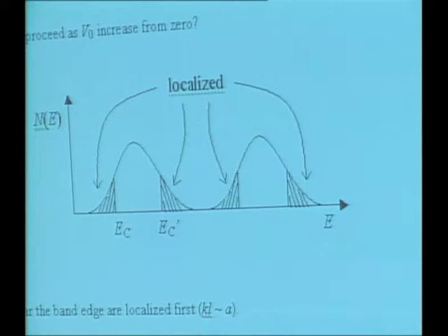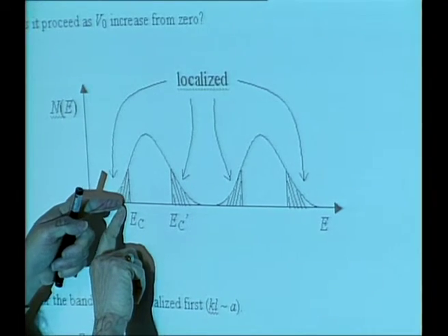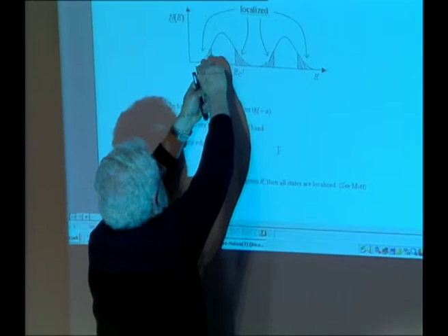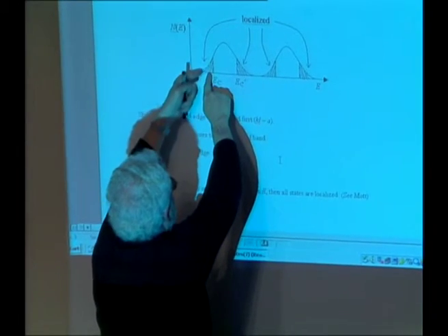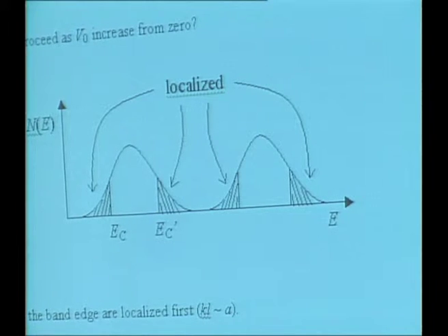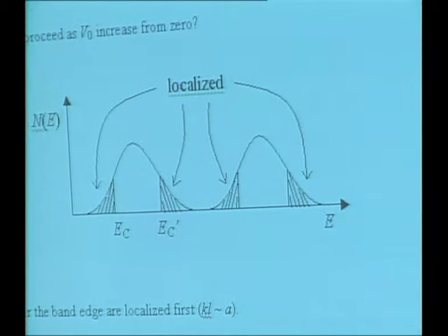Okay, so in this example, if the Fermi level were here, then you'd have to have activation of electrons above the mobility edge in order to get conductivity. If the Fermi level's here, all these states are empty. But even if you thermally activate into those states, they're localized states, so nothing can move. So you have to come up above the mobility edge. Now there is a more clever way to do that, which is called variable range hopping, and I'll tell you about that in a minute.